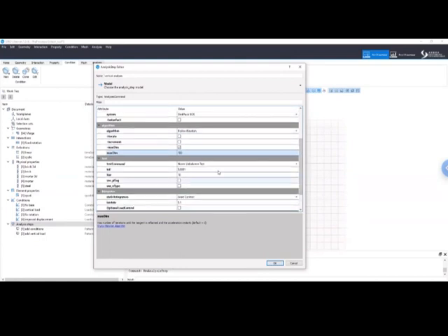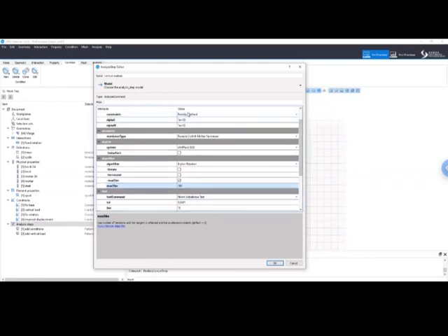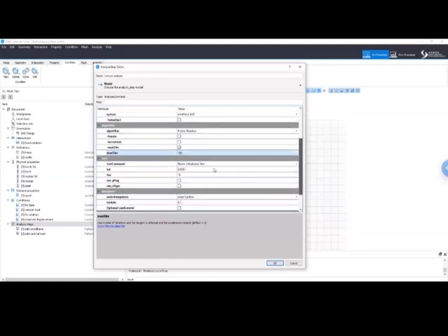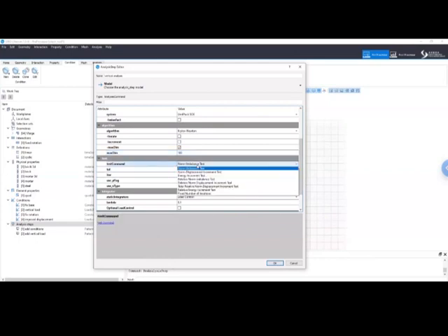Now, this one instead is very important. By default, this is the convergence test. By default, we have a test on the unbalanced force, so on the residual. Unfortunately, when you use the penalty method, you cannot use a convergence test based on the residual vector. You need to use a convergence test based on the solution vector, so either the displacement increment or the relative displacement increment. So in this case, we choose the displacement increment test.